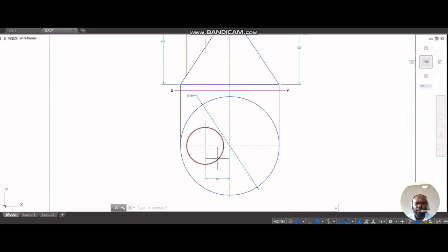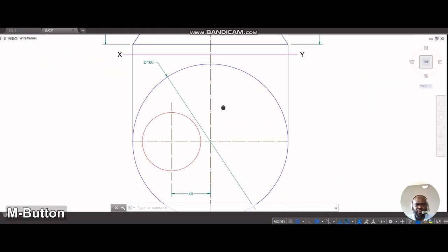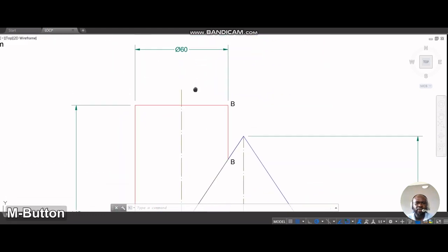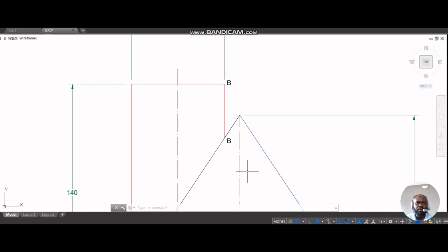So we have all the dimensions set here. So we would look at that and start solving the points. So let's start. The first thing to do is to draw cutting planes through the two objects to be intersected. So we're going to do that.